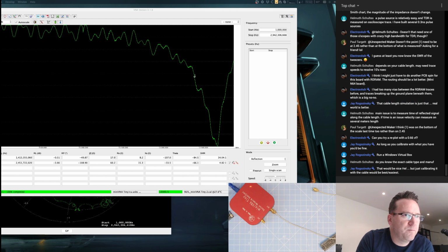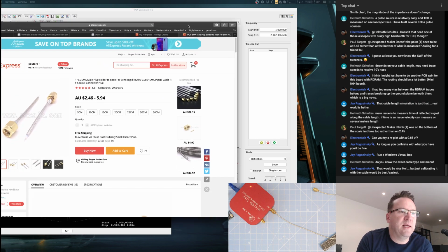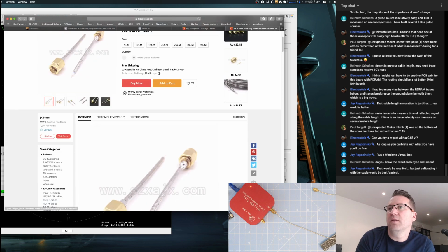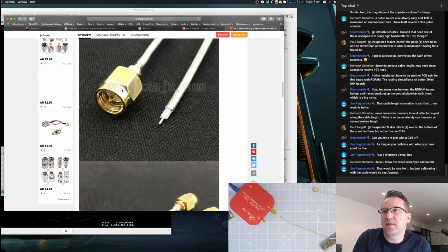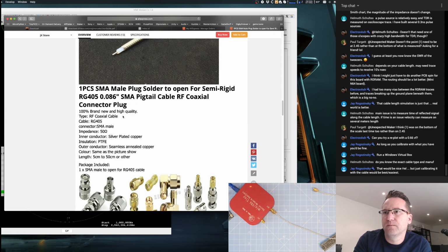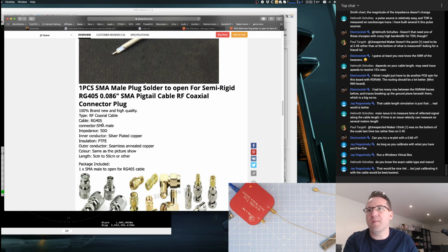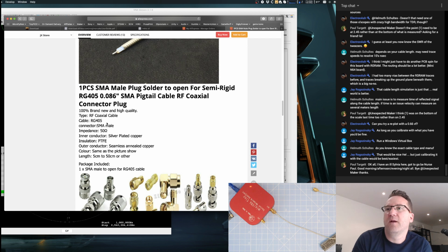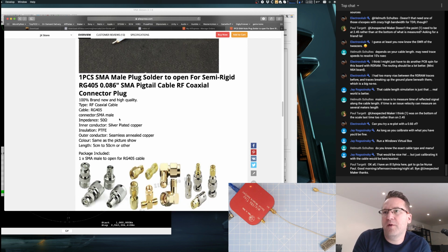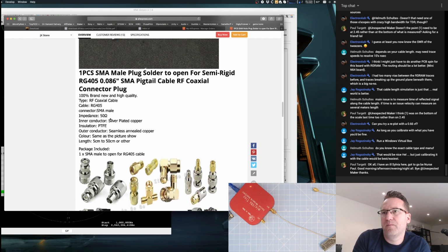Okay. So here's the link to what I got. Let's see what it says. Okay. Yeah. See, type RF coaxial cable, RG405. Insulation, PTFE, silver plated copper.